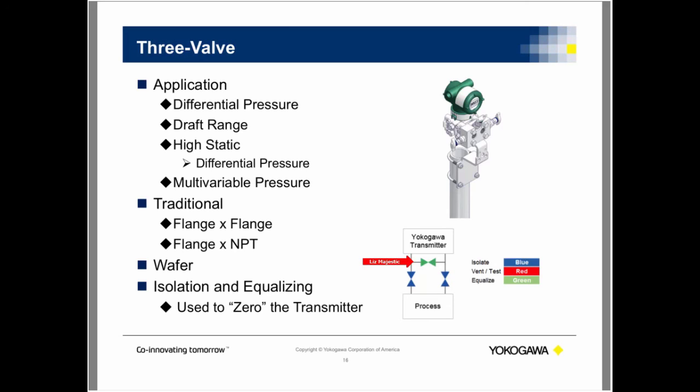So you're basically going to recheck the zero. Then you're going to replace the pressure from the instrument through the low side vent screw and observe the zero. Most of your transmitters are going to have a vent screw on the side or on the back. So you're just going to open that up and observe the atmospheric pressure, or the zero at the atmospheric pressure.